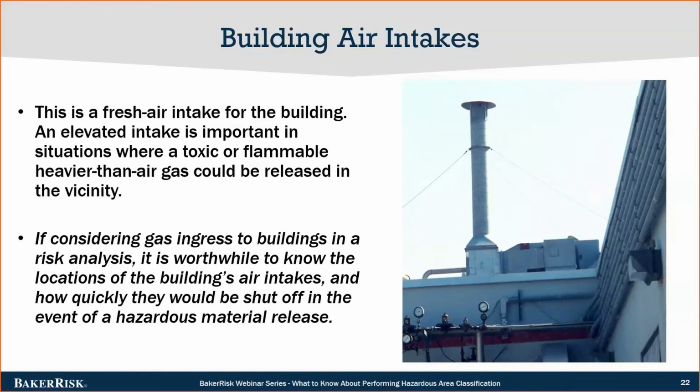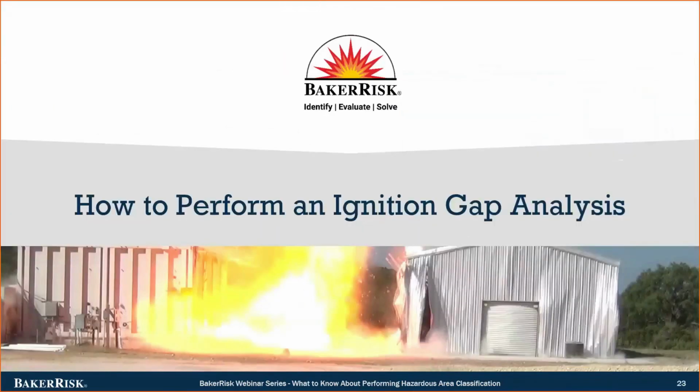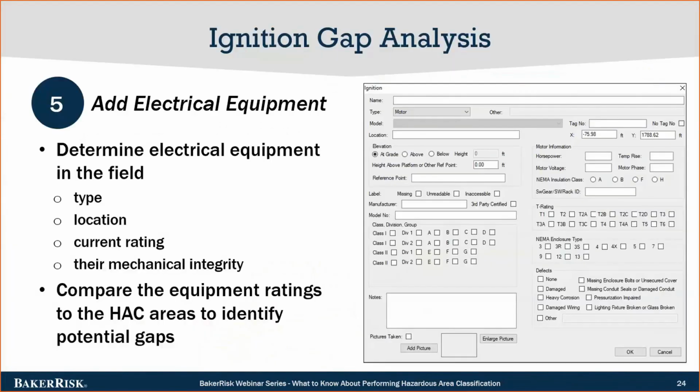Moving on, we're going to look at the ignition gap analysis. The ignition gap analysis is an important step because this takes the transition from the actual modeled hazardous area contours, which are those areas that we've defined as being areas where we want to use special equipment. And we want to verify that the equipment installed in those areas does in fact agree with or is suitable for that defined hazardous area classification.